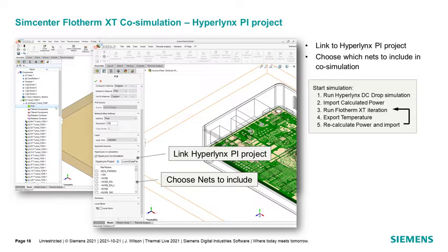We have an opportunity to change the conductor material, the dielectric material, and also the via fill material. And these are all going to affect the material map calculations. It shows the PCB source was EDA bridge, and then you have the resolution, how much you want to resolve that material map, either fine or averaging. So like I said, if you use fine, you get two nodes across the smallest trace. Also, for via fill material, you can choose void if there is no fill material present.